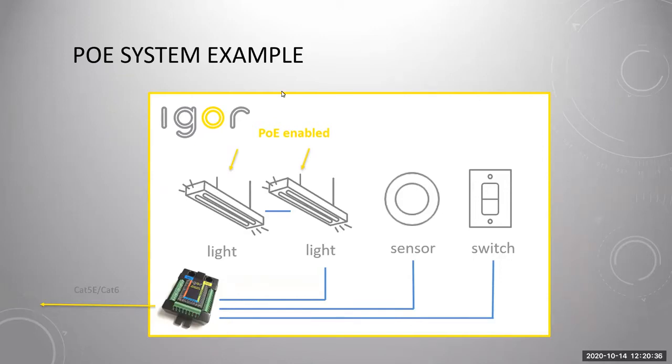You also asked about BACnet. We have a BACnet over IP add-on module that will allow for incoming commands to the lighting control system via BACnet over IP. And then we recently expanded that capability to send outgoing commands via BACnet over IP, primarily targeted at other lighting control systems that are BACnet enabled. But we're hoping to expand that to also HVAC communication via BACnet over IP in the near future.